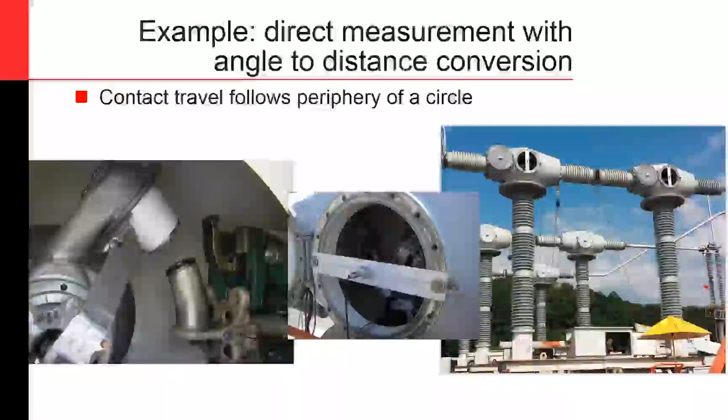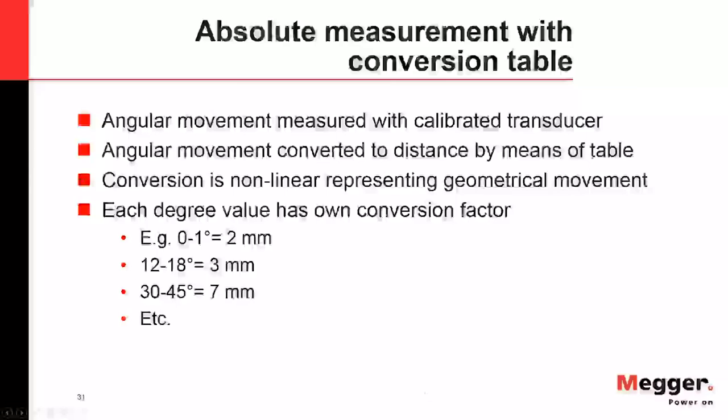What you do is you open up these tanks, of course, to evacuate the SF6 gas and hold it and everything during testing. But you open up these tanks and then hook that transducer right on the center there, and that transducer would rotate along with that interrupter. What you want to do is convert that rotational value to a linear arc length value to get that interrupter actually moving back and forth on the left there.